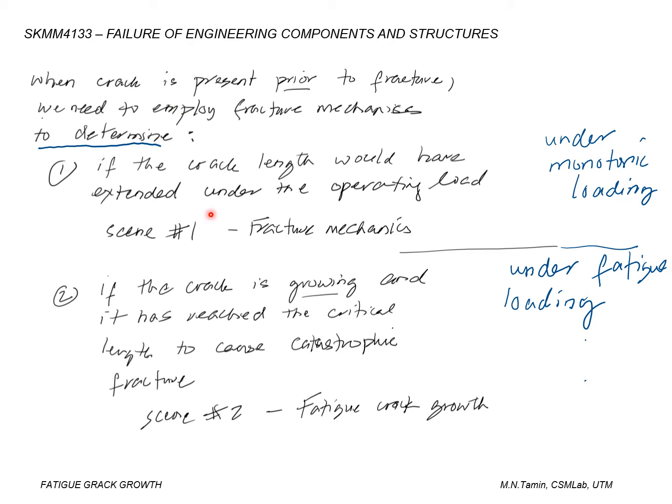However, if the load is fatigue and it changes with time, then we need to determine if the crack that is growing has reached the critical length, the maximum length to cause the fracture. This is a case where we need to use a fatigue crack growth analysis in our failure investigation.